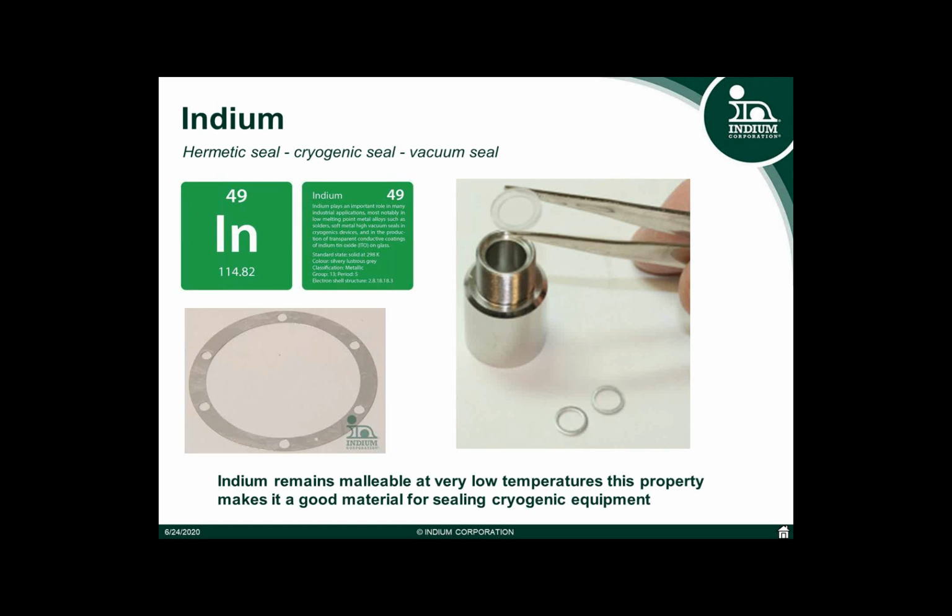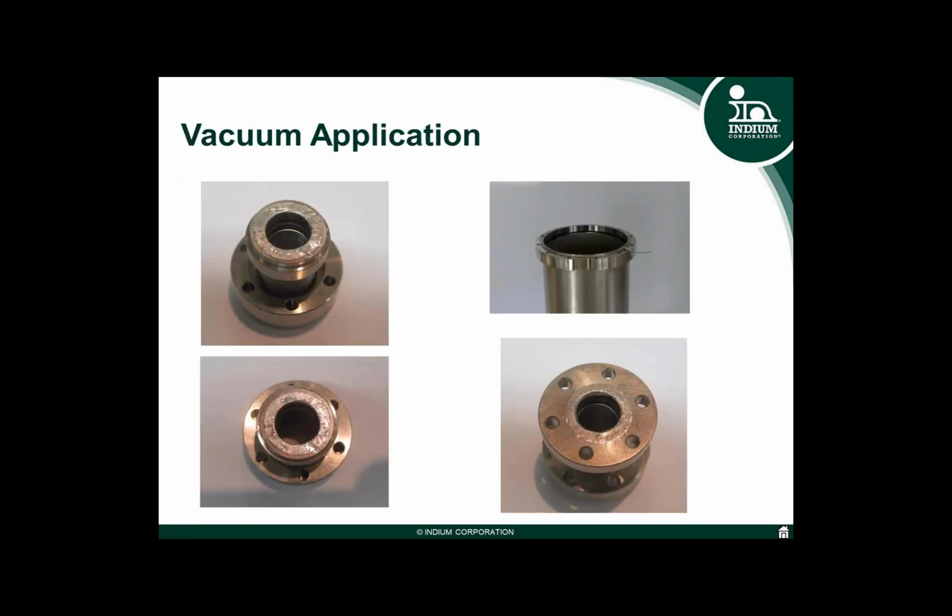Here on the right hand side, you can see it's actually just been used to seal a lens. But in the following application, again, it's in a semi-high pressure application where it's been used as a gasket operation, so sealing two bits of hardware together. We can see that the shape form can be in a traditional washer format, or it could be, as illustrated before, wrapped as a cylinder, so a solid wire. It's very easy to form, so it could be made that way.